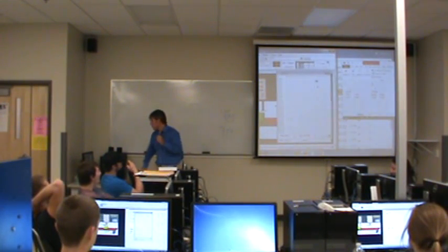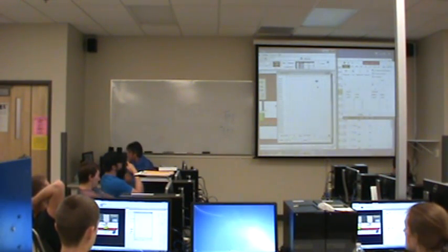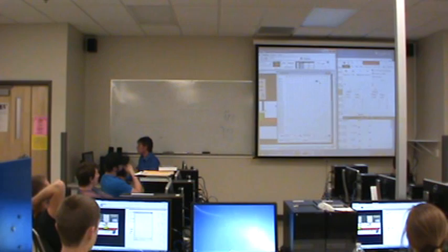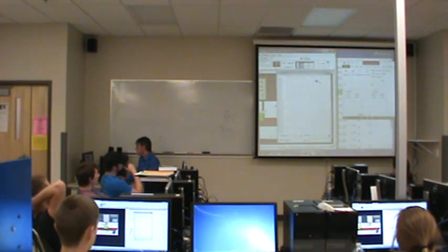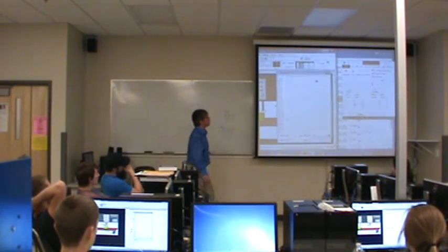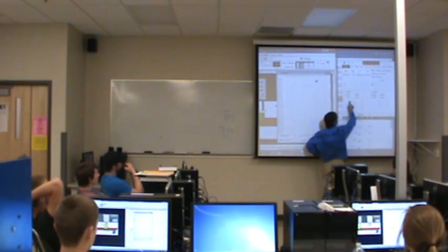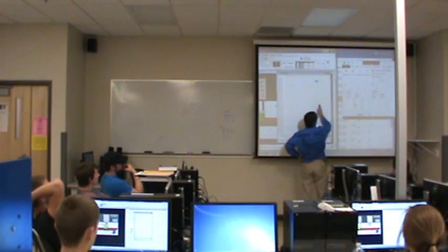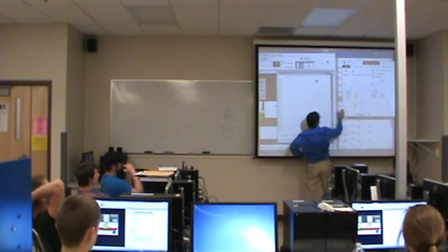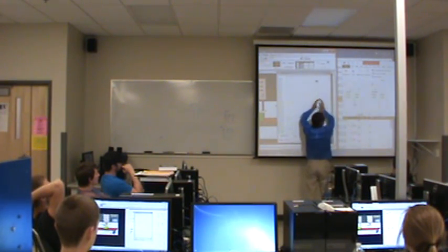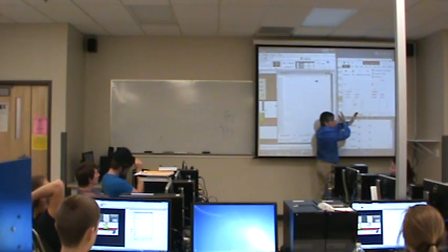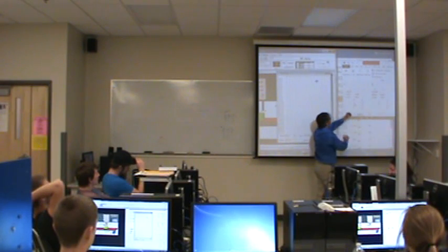Okay? So I need to see that input 3 and input 4 are off. Okay. Next, I would like to see that input 3 is on. Now be careful here. I purposely put these two backwards. But this particular line of bits deals with bit 3. And this one deals with bit 4. I can't just take these and copy them over as they are because I'd have them backwards. Does that make sense? So I have to be careful.